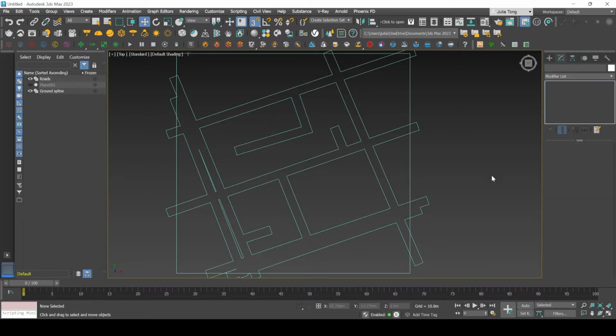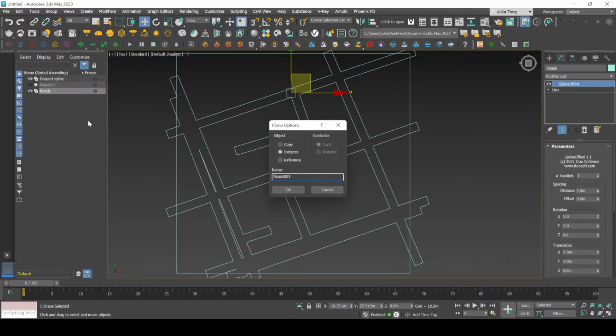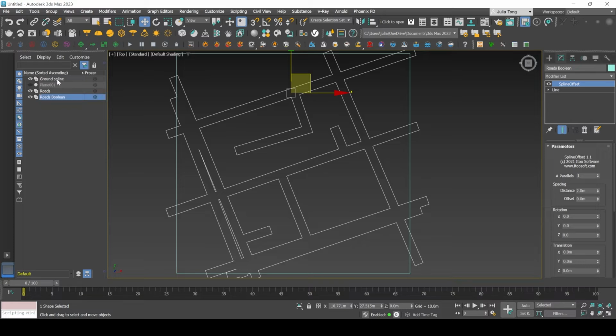To create the land lots, which will be the areas where the buildings will be standing, we will need to do a shape Boolean. Shape Boolean is a spline-on-spline operation and cannot be intermixed with geometry. Make a copy of the ground and the road spline. The copied splines cannot be recovered and will be stuck as a Boolean, hence we make copies.